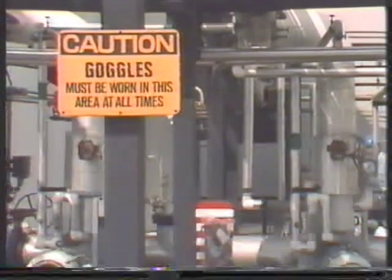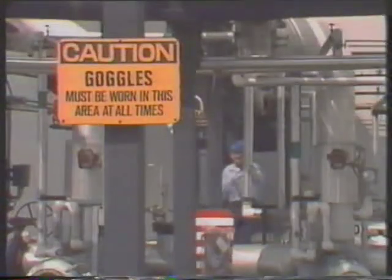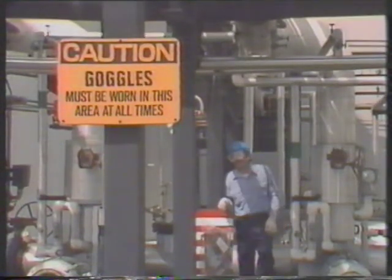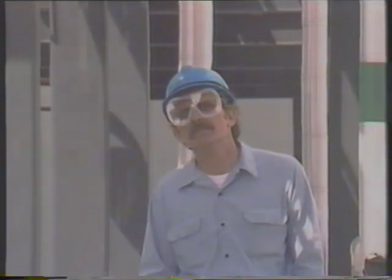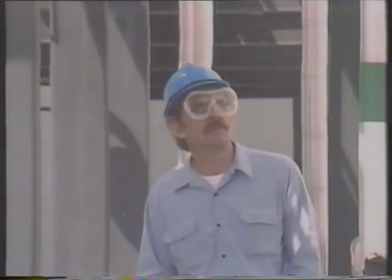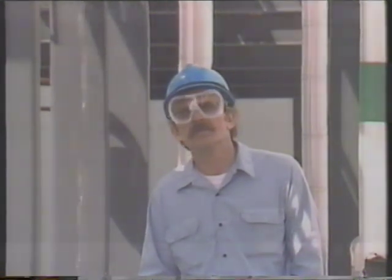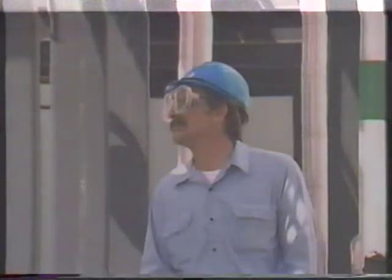Safety goggles are also required in many work areas, particularly work areas where overhead pipes could drip chemicals that can irritate or damage someone's eyes. When goggles are worn properly, they keep dust, flying particles, and splashing liquids from reaching your eyes. Most goggles can be adjusted for a good fit. They should fit snugly against the face.